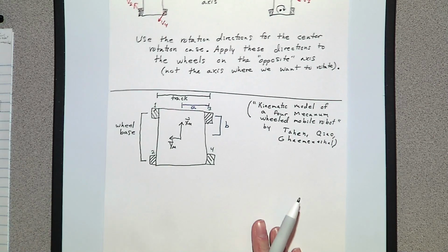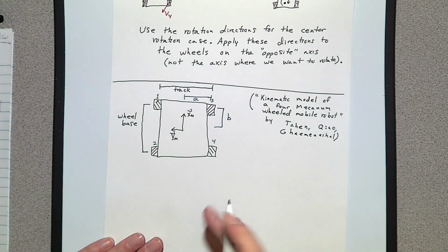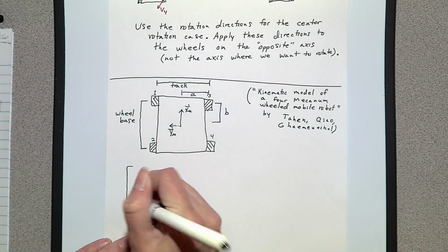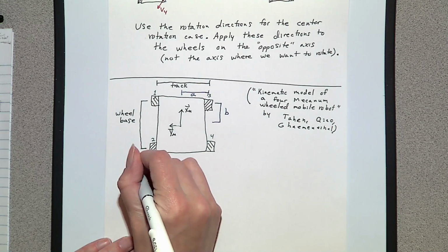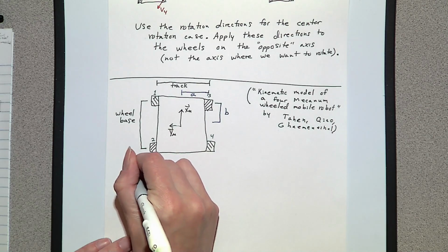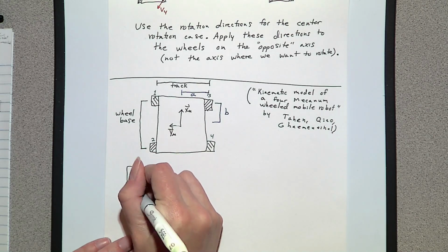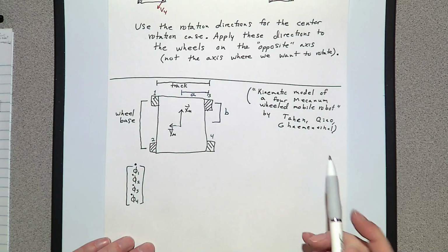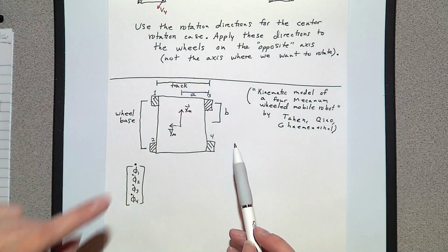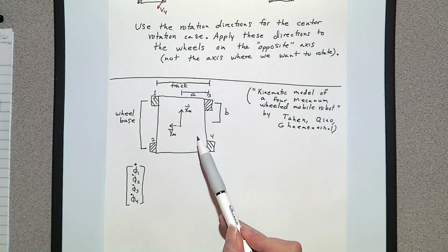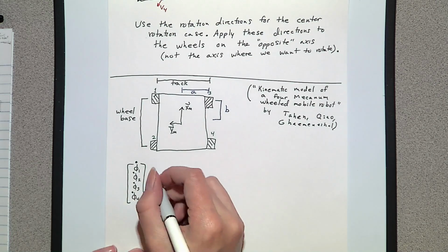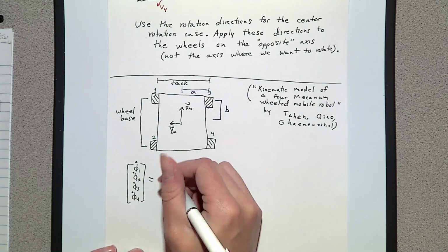But you take those and you combine them, do some simplifications. Then we have the rotational velocities of each wheel. And note that our wheel number order is different for our model than what it was for the robot in the paper. So you'll notice that there is some difference in the two models, but the derivation is the same.